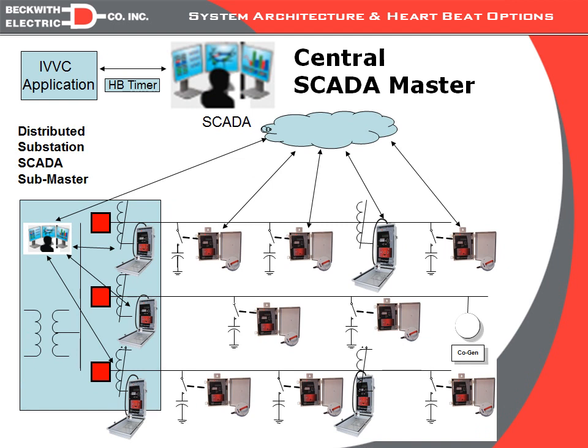And again, we have the distributor to the combined approach. In this approach, again, the SCADA Master may be polling some of the controls directly, but we may have an intermediate RTU polling other controls. So again, if we were to use the standard heartbeat, it may work in these, but if this link goes down, the RTU would still be polling, and therefore these controls would not know to come out, and they would stay in remote manual.